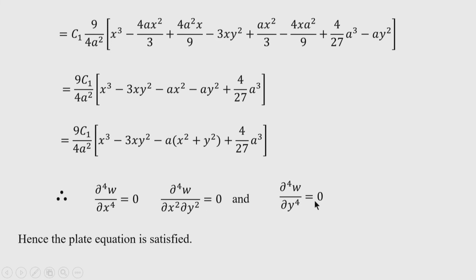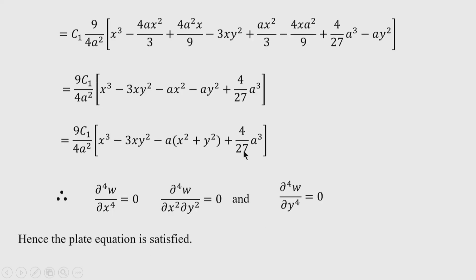So, the differential equation is also satisfied, because we have found del 4 w equal to 0 in that case, because no distributed loading is there, no applied loading is there except the edge moment. So, q is 0. Therefore, the differential equation is a homogeneous equation, and by taking the expression of the deflected surface with this form, it is easily verified that the differential equation is satisfied. So, the plate equation is satisfied, that is our inference.